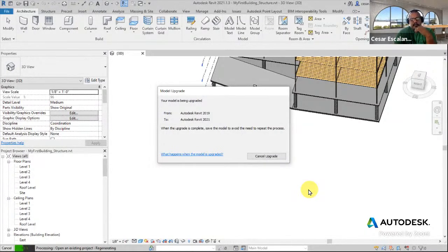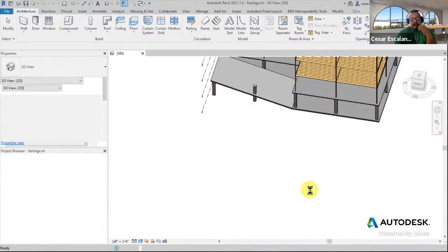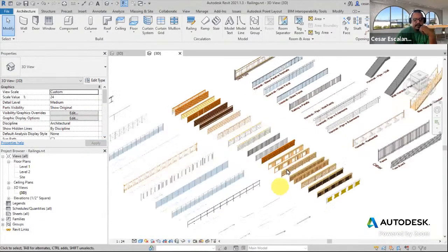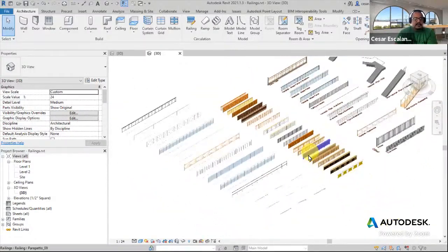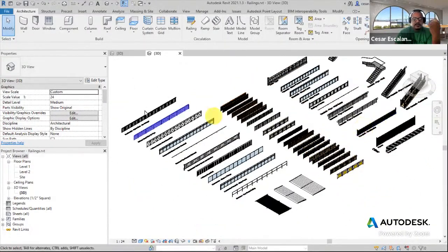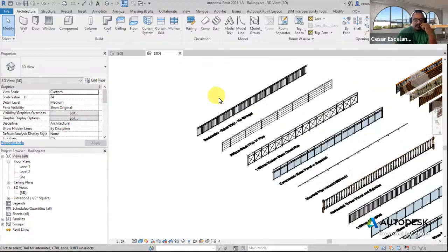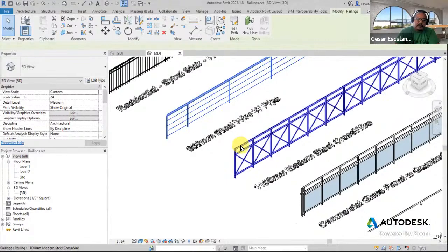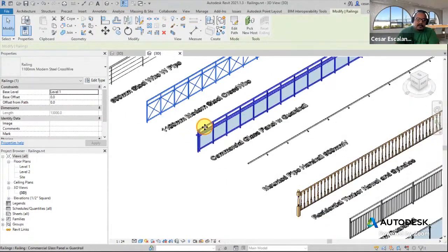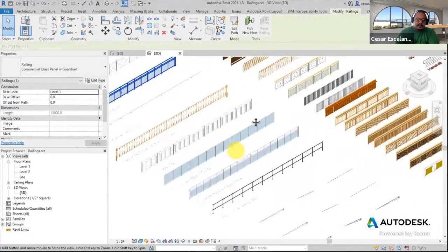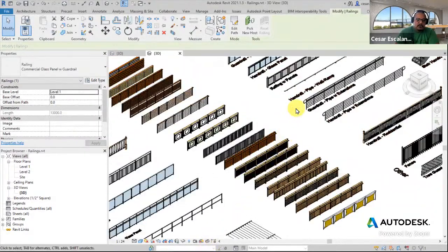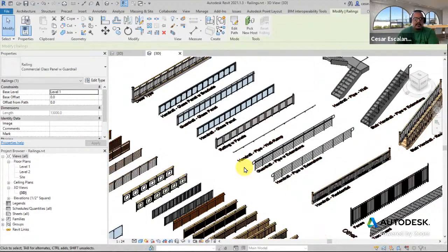So the railings, it's a system family, but it's very like the curtain wall, made of different components. This is a container file, and you're free to use it for work if you want. These are multiple definitions of railings arrayed in a tabular display. And in fact, in your practice, you should have something like this, so you don't have to start from scratch.